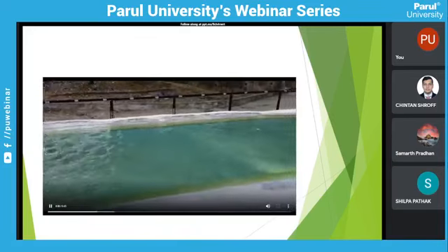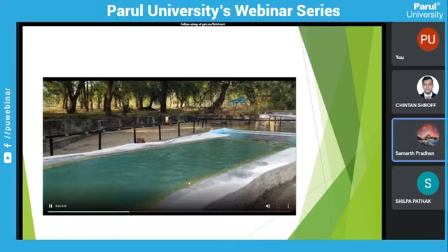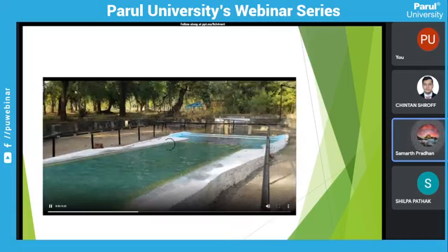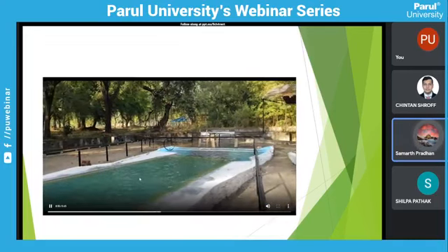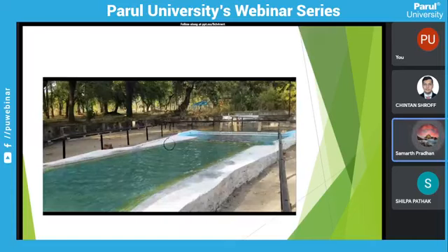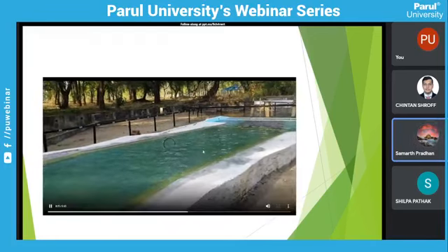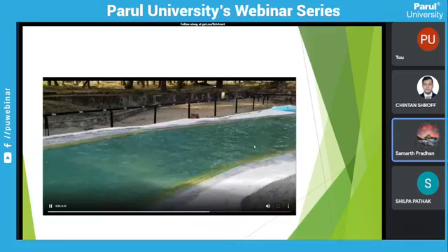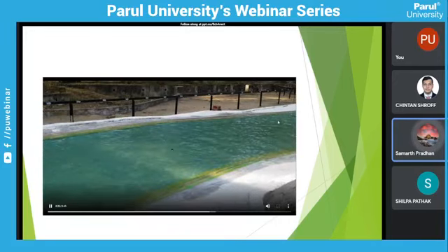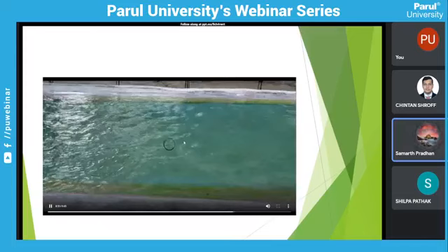Discharge 7.2 lakh cubic. See, this model is running at 7.2 lakh cubic discharge. Here also an anicut is there, because whenever a riverfront is suggested, mostly in cities, we need a particular pool of water all over the year. So for that an anicut is proposed here, so that you can get a water pool throughout the year. That anicut is tested, and on the downstream of the anicut, nearby, there are 3 bridges: 2 overflow bridges and one low level causeway. We have tested all those bridges.